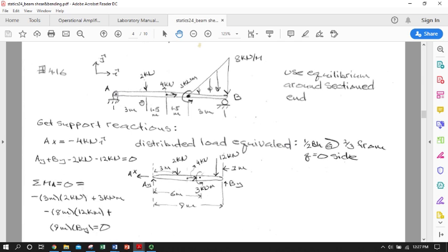So we are going to apply the same principle we did before to each one of these sections. We're going to go from the left hinge to our applied point load. We're going to go from that point to where we have another applied point load. And then from that point to where we have a point applied moment, and then the remaining section where we have all of the above plus a distributed load. So we'll have 1, 2, 3, 4 sections.